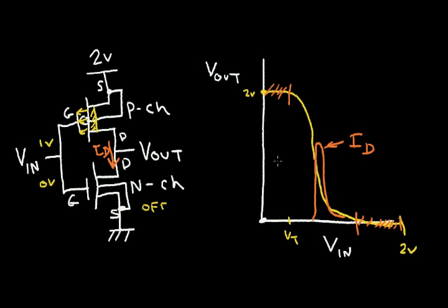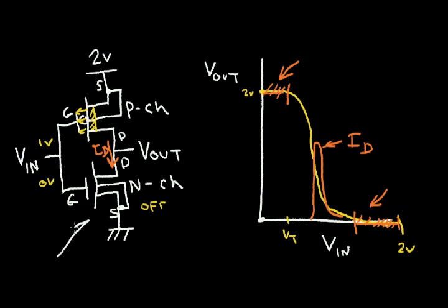So the beauty of the CMOS inverter and CMOS in general is that when the transistors are just sitting there, where say the output is at a high voltage or the output is at a low voltage, in both cases the power dissipation is almost nothing. So we could have a lot of inverters and similar circuits on a CMOS integrated circuit and the power would be quite low. The chip wouldn't heat up that much. And that's a big, big plus when you combine a lot of transistors together to do different functions. And that's the beauty of CMOS, is that you can combine a lot of functions together and not dissipate much energy. So let's talk about the CMOS inverter in more detail. Let's draw the symbol for this CMOS inverter.